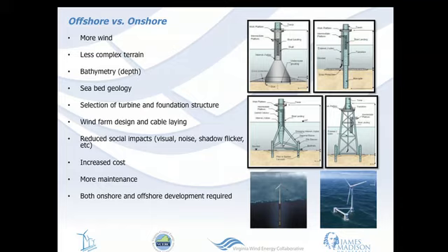On the left, you have your tripod, which is essentially a monopile, which is driven into the seabed. So you have to basically hammer your foundations into the seabed using a special barge called a jack-up barge. These vessels are mostly available in Europe and in the Gulf. So getting them to Virginia would be very expensive. Renting these vessels costs probably $10,000 a day at least, if not more.